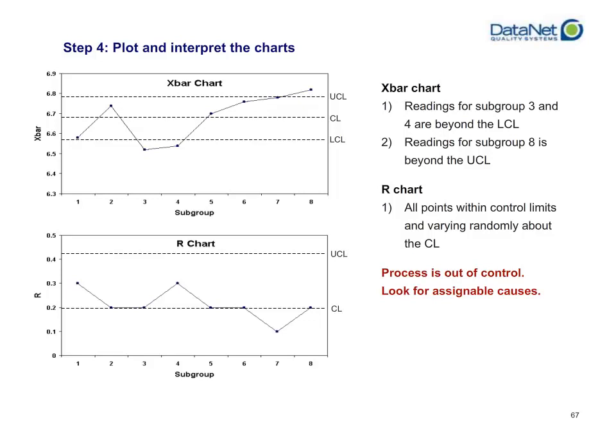You're going to go ahead and plot all 8 X-bar values that you calculated in step 1 into your control limits for your X-bar, and then you're going to put your R values into your R chart, the ones that you calculated from step 1. Now that you have plotted your X-bar chart and your R chart, you can begin to analyze what you have drawn or what you've plotted.